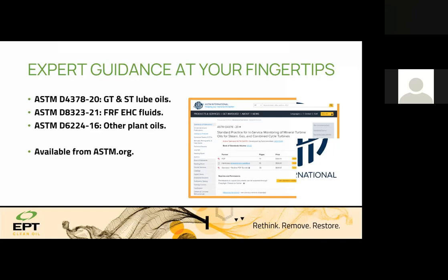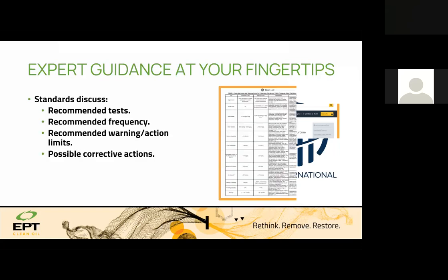I can say $60, $70 is the maximum price of them. Having the best guideline in front of us, which is an agreement between all the stakeholders, is a very good starting point for making an oil analysis program for a critical asset like a gas turbine or a steam turbine. And then the standard discusses the recommended tests and what frequency to do, for example, every month, every 3 months, or yearly,